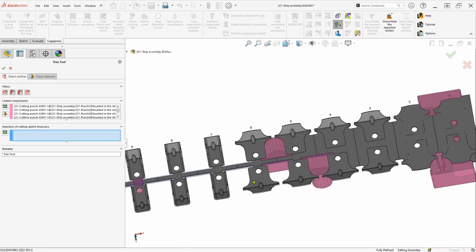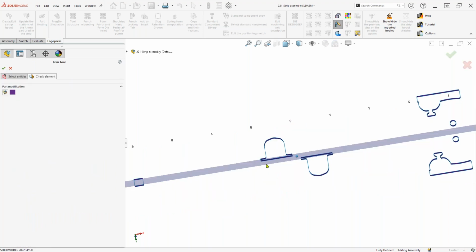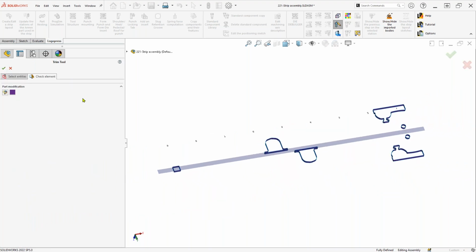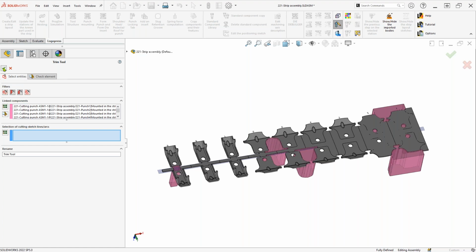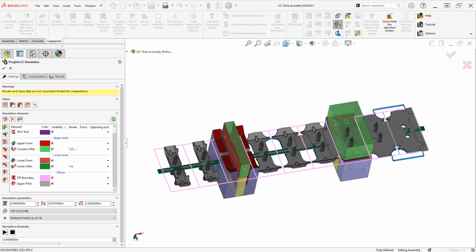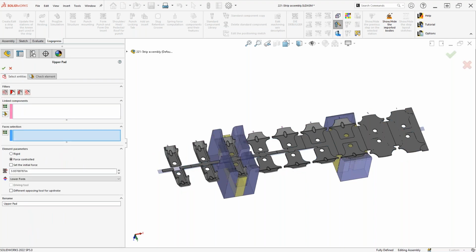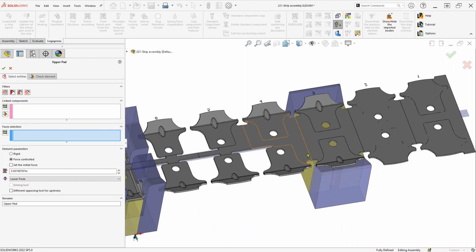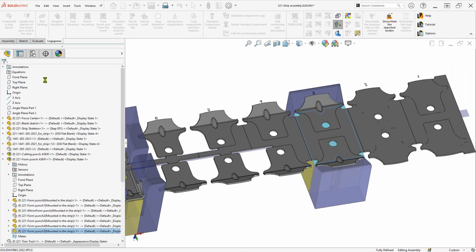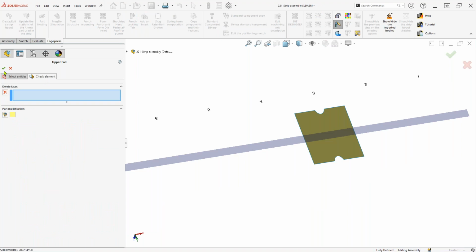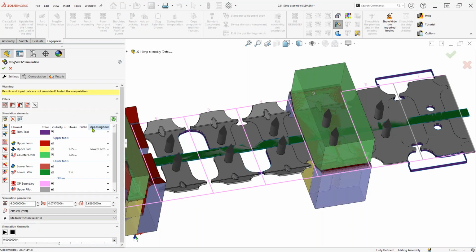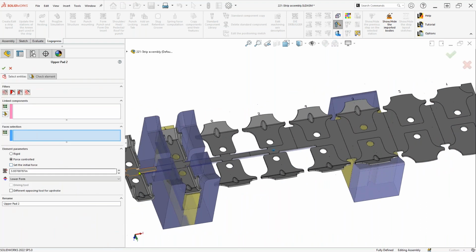The last one here is the trim tooling, because it is starting at the regular coil. It should grab all your cutting punches automatically from the strip layout. So that's for all the basic tooling there. You can start adding more types of tooling from the left column there. He added a pressure pad, which is spring force controlled here. Again, it's the same format of picking the surfaces that you want for it. You can define a stroke, and then you can either ask the software to calculate the amount of force needed, or you can enter an initial starting force to begin with.